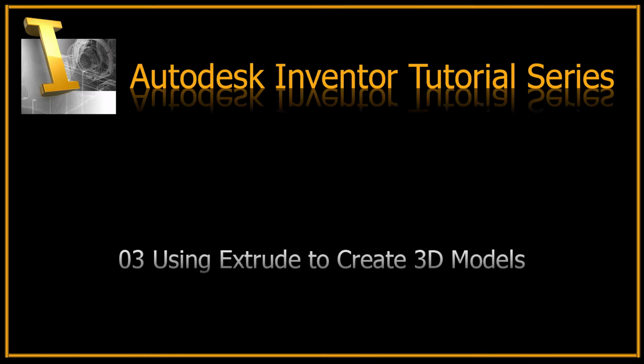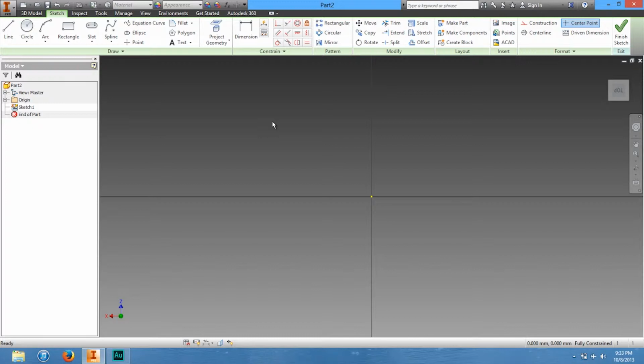In this tutorial, we'll be creating a 2D sketch and creating a 3D model. So start by creating a 2D sketch and then select the rectangle tool. Snap to the center point and just go left and make a longer rectangle, kind of like this.